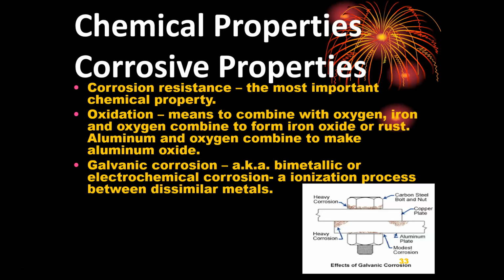Some plastics are destroyed by sunlight and oxygen. Rubber oxidation is a result of aging. As it ages, it loses its elasticity. Water absorption, the tendency of polymers and ceramics to absorb water. It increases the material's weight and volume and causes them to warp and swell.